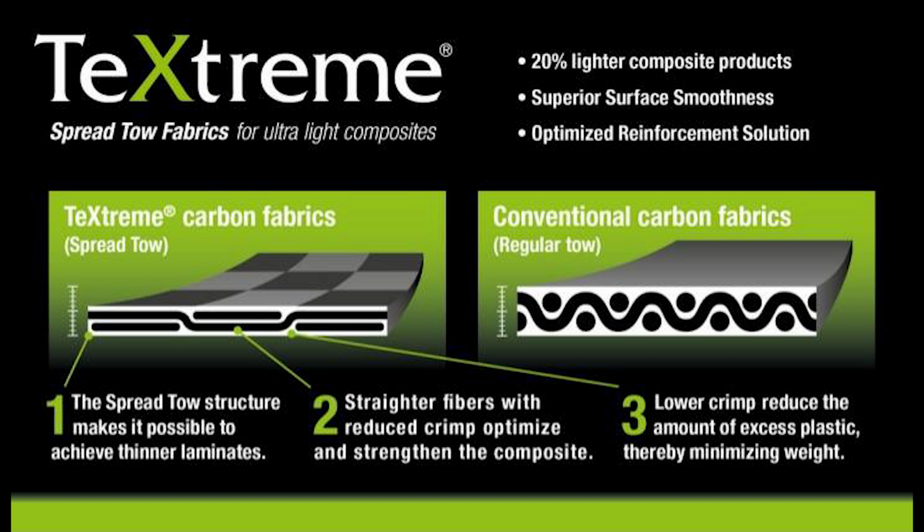So the properties of this weave are very close to a UD, but half of the fibers are going along the arm, and half of them are going perpendicular. Because the fabric is thinner, you can move the next UD layer underneath further out without making your laminate thicker and heavier.